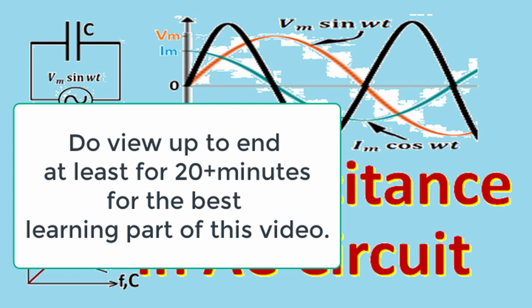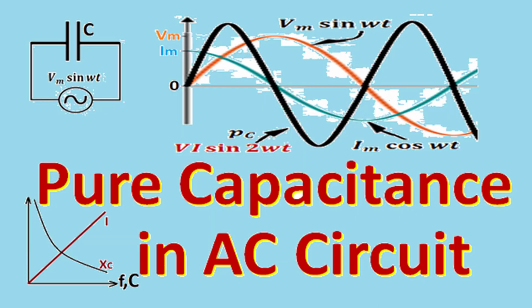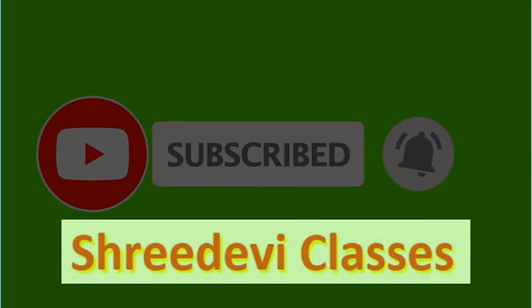And in this condition, capacitor stores energy when voltage increases and releases the same amount of energy when voltage decreases, and average energy consumption in a cycle or long duration will become zero. And we say such current, which is 90 degree leading to voltage in phase, is reactive current, and power associated in this current flow from voltage source is reactive power. So let's understand pure capacitance in alternating current supply.